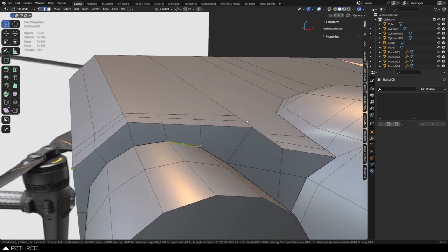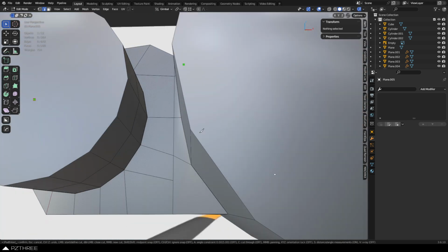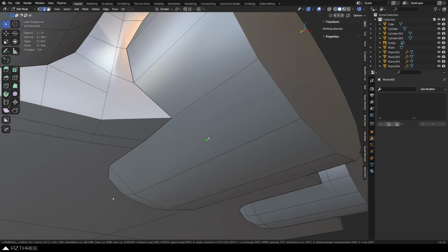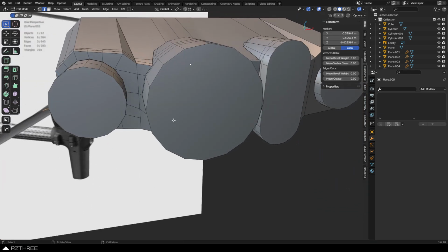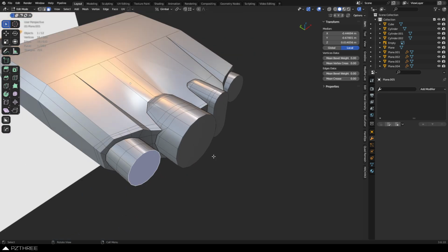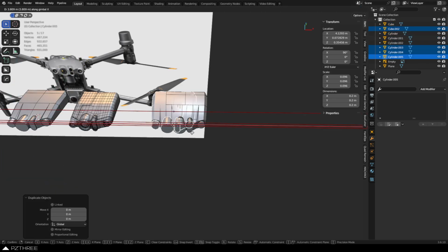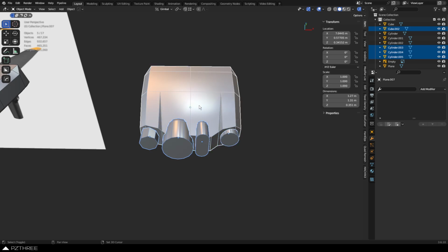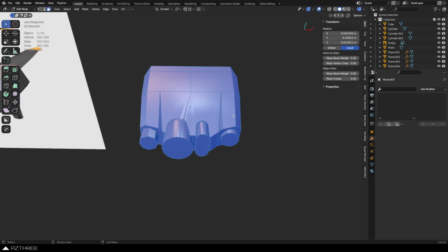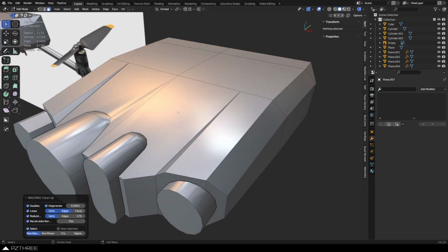You see all these want to just run out like so. The top's fine, the bottom's not fine. All right, and so yeah, we keep doing this. Now here's the trick. Real quick, I want to show you guys something. We're going to do these again. I'm going to bring it out here. We're going to shift double click this, Control Shift B into our auto Boolean union. I'm going to run the machine tools cleanup feature, just make sure everything's merged.